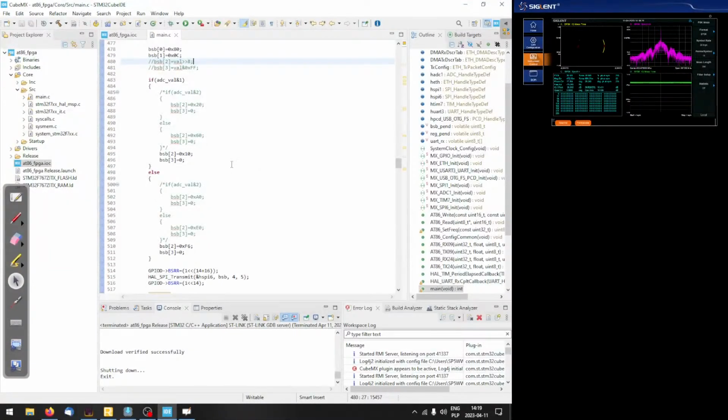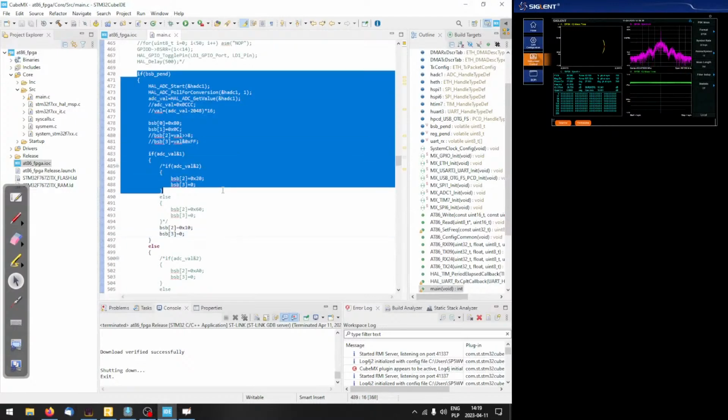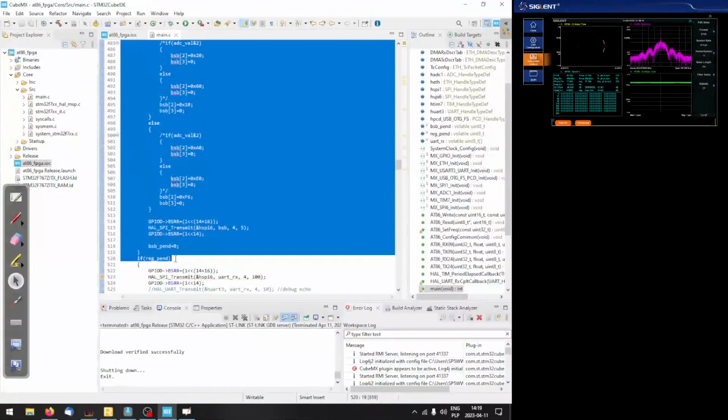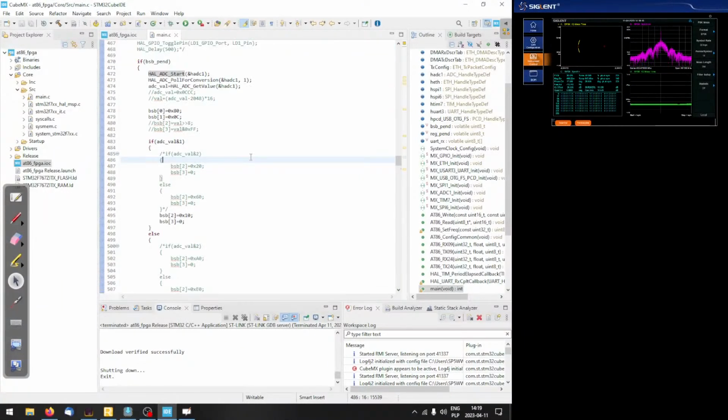Let's take a look at what's actually being sent from the STM32 to the FPGA. If you remember, we've got a piece of code running on the STM32, and this part is executed 24,000 times per second, fetching a new baseband sample.